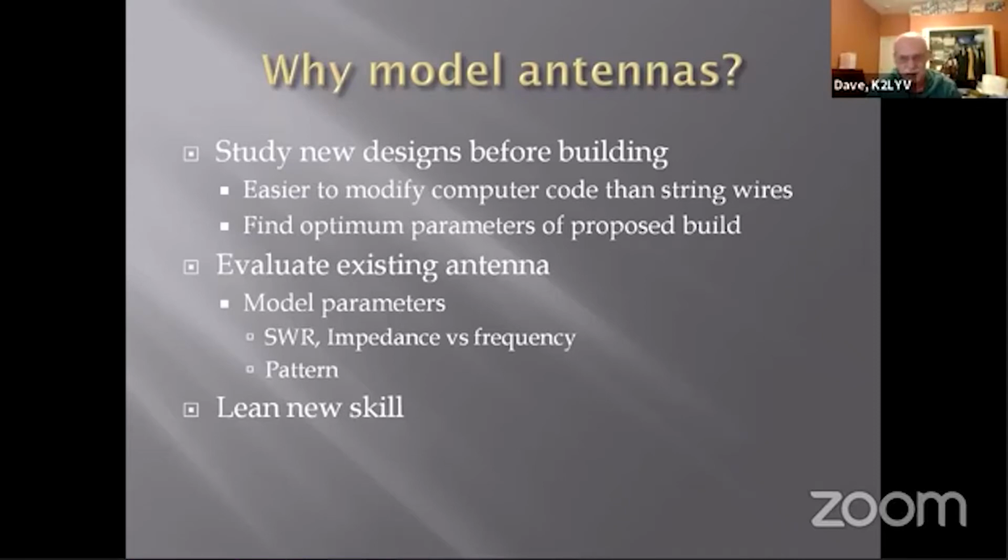And without having to go out and make measurements, you can, in the computer, see what the SWR would look like, what the impedance of the antenna would be versus various frequencies, what the pattern might be like. And even if you then go out and do all these measurements, the modeling has given you some idea what to expect.